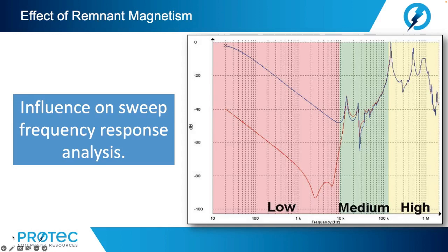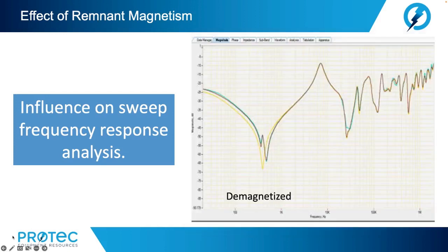The plot of a fingerprint should not change throughout the entire life cycle of a transformer. All influences which could affect SFRA measurements must therefore be avoided, as they could lead to misinterpretation of the obtained test results. Now, the SFRA measurement reflects the main inductance through the first resonant point. The FRA signature shown here shows the typical resonance point of a three-limb transformer's main inductance.